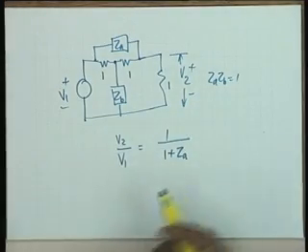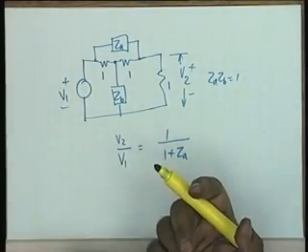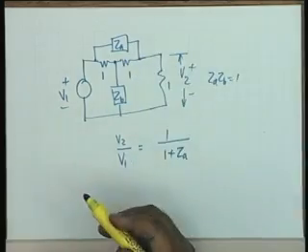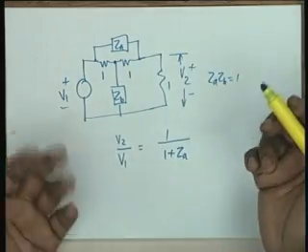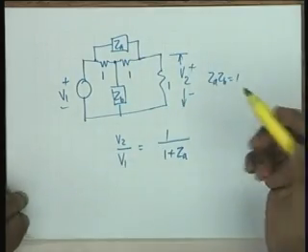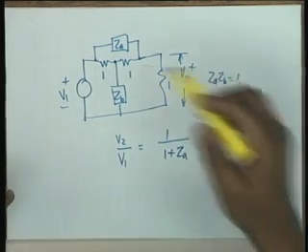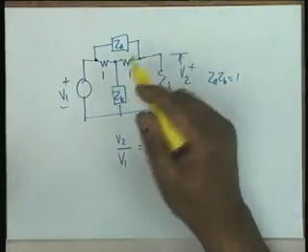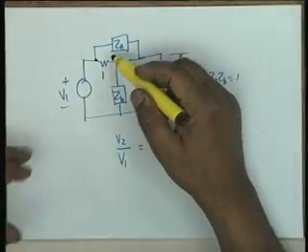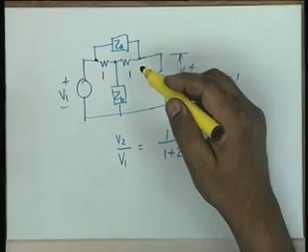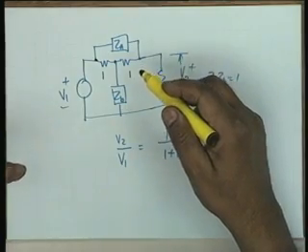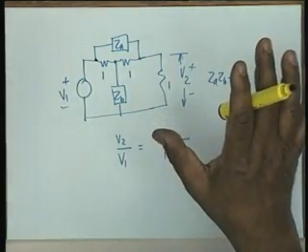Okay, you can do it in the same manner that you did. You could convert this into a pi, combine with another pi, then find out the transfer function and so on. To bring variety into experience, let us do it in a slightly different manner. You remember I pointed out that if there is a voltage source connected to two networks, you can think of this as two networks in parallel. Then you could split the voltage source.